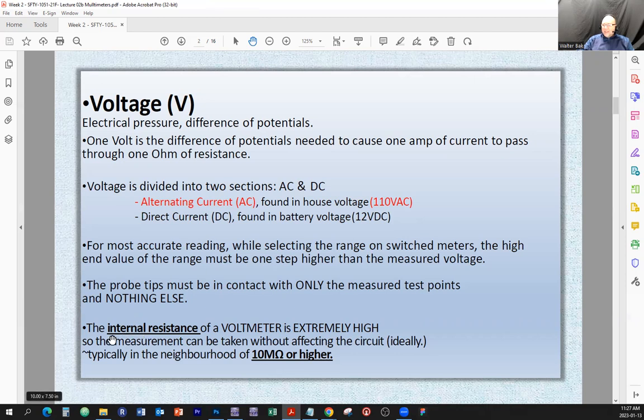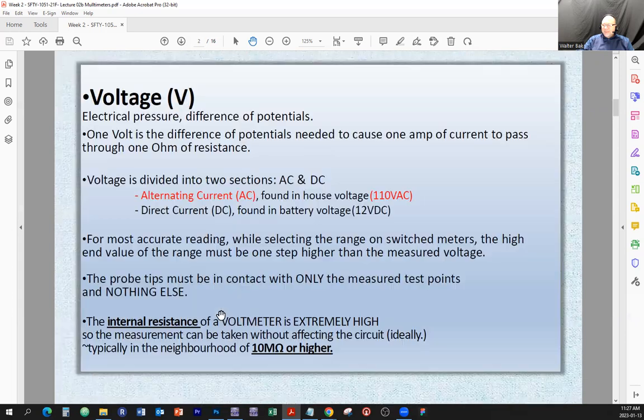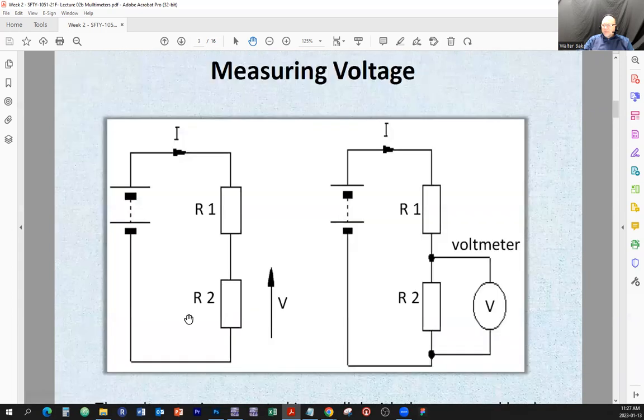I'm going to come back to the last part here, but first, this might help you with other subjects as well. If you are assembling any kind of circuit on a breadboard or on any kind of training board, concentrate on the current pathways first, and then see what parallel devices are to be added.